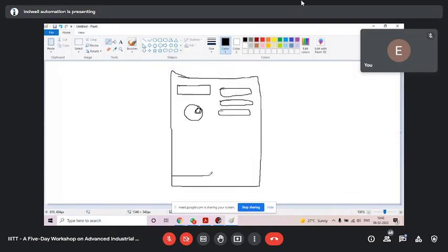Now you see its power supply. This power supply you will have to check. The AC drive we are going to use here has a power supply of 230 volt AC single phase, right? 230 volt AC single phase. So if your power supply is 230, then your output will also be 230 only, where you connect your motor.